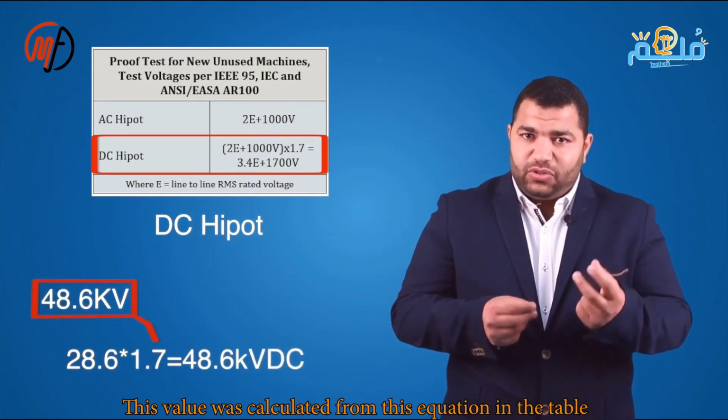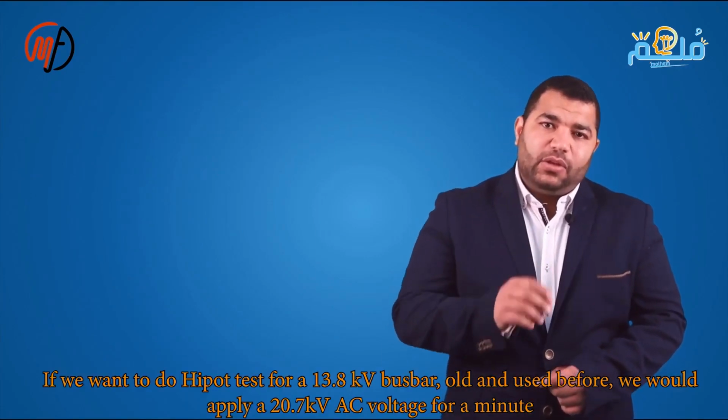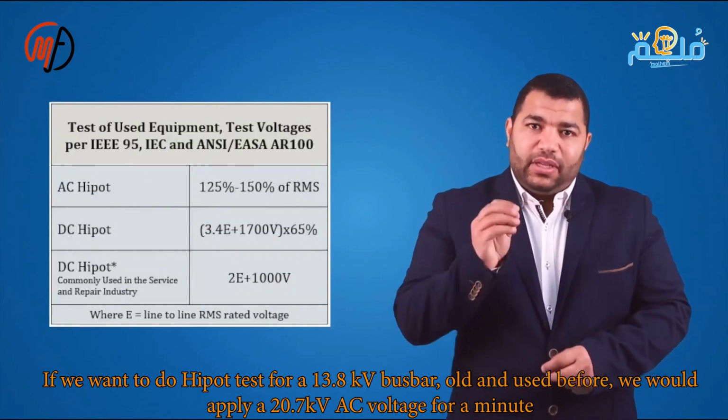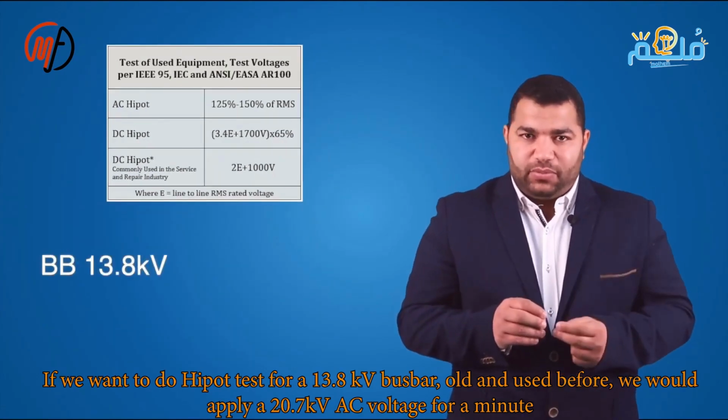For older equipment, use this table. For an old bus bar rated at 13.8 kV, apply 20.7 kV AC to each phase for 1 minute, as per the equation, 1.5 times 13.8 kV. For DC, apply 31.59 kV, since used equipment voltage is 65% of new equipment voltage.